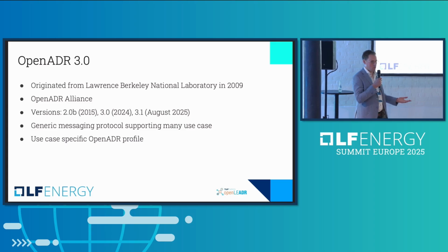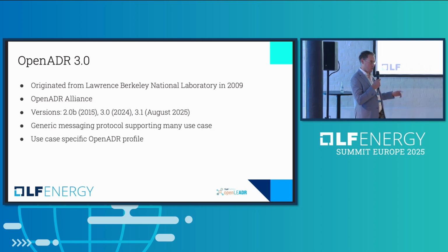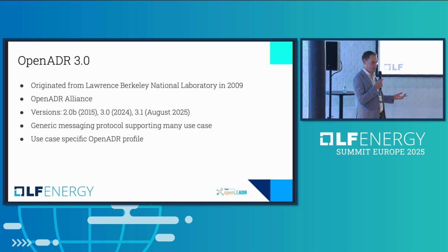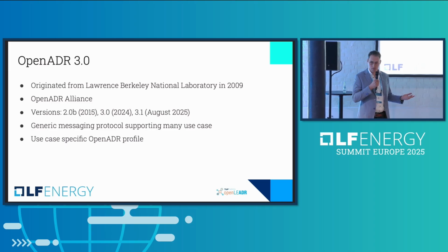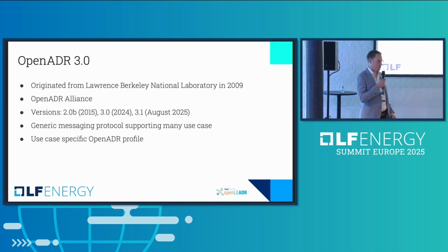The OpenADR protocol is very broad in the sense that it supports a lot of use cases. So it could be about power limits, but also pricing based. If we look at the USA, where this originated from, they do a lot based on pricing, where we in the Netherlands at least use it a lot for just communicating limits and surplus in the grid, for example, that you can actually use instead of doing everything pricing based. But it supports all these use cases.